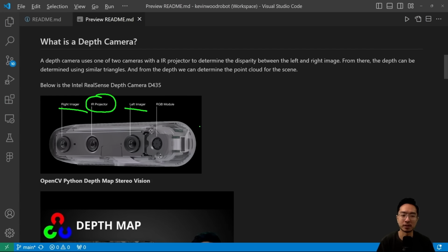So now let's take a look at how we could set up our depth camera Gazebo sensor for our URDF file. Previously we used our head to camera transform in the Gazebo section, but now we're creating a new joint for it, and we'll explain the details of that later on. So we're changing this pose, which took care of some of the transforms, and now we're setting the pose to be all zeros. And then we're going to be creating 2 links. So we have one link here called the camera link, and then another link here called the camera frame link.